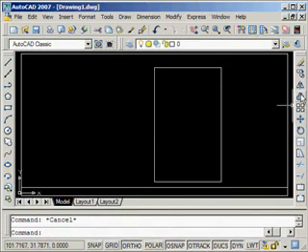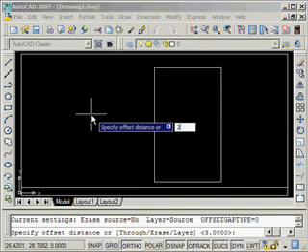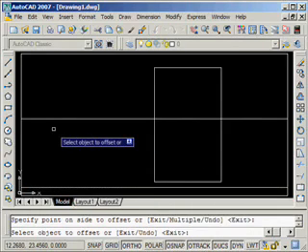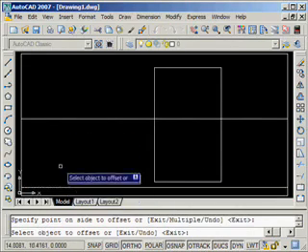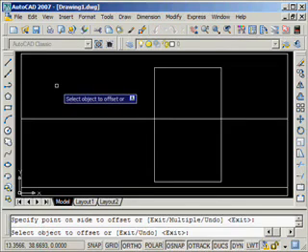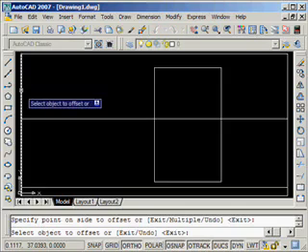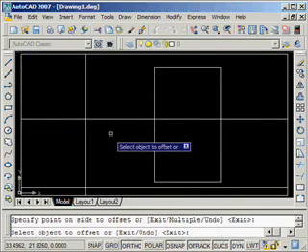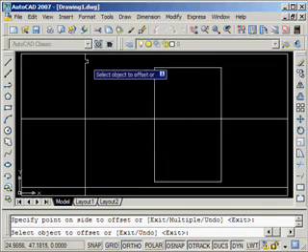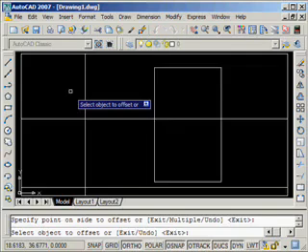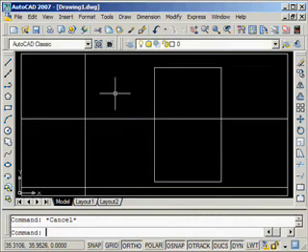Go over to the right here, I'm going to grab offset this time from the toolbar, type in 24, hit enter. My garage is 24 feet wide. So first I select the line that I just drew, offset it to the north side. Now it's asking me again, without re-entering the command, the unit it's using is already 24, which is how deep my garage is. So again, I'm going to pick this back line and offset it to the right, and it draws a new line 24 units from the last one perpendicular to the side that I chose. Hit escape a couple times to clear that.